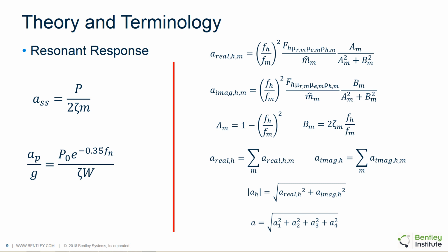You'll also see that the only real terms in here, in addition to damping, is the natural frequency of the structure. And so we only get one natural frequency, no matter how many modes we have, and the assumption here is that the predominant vibration frequency is going to be the fundamental frequency. And that may be true, but it may not be true for irregular structures.